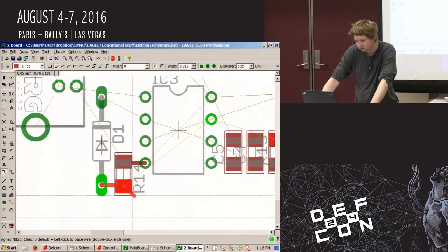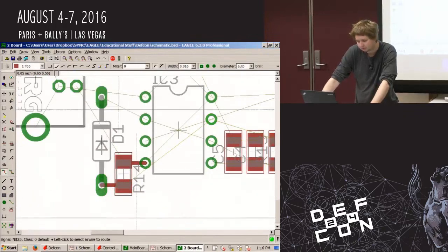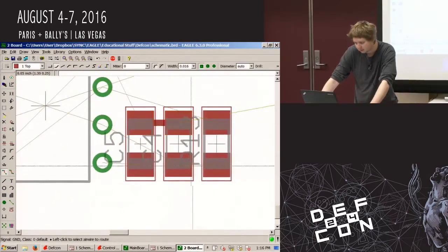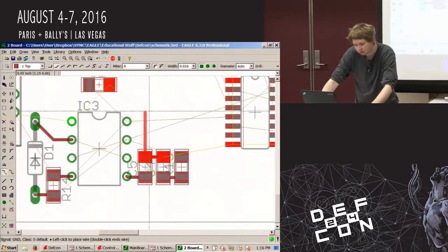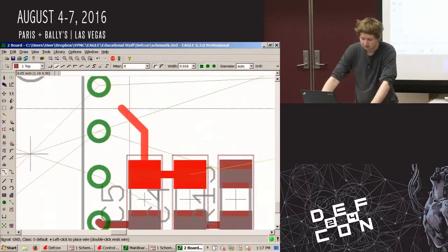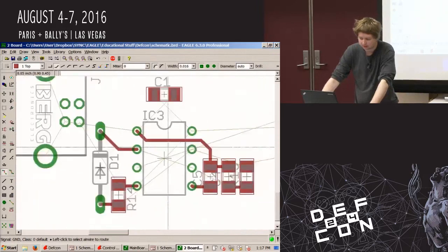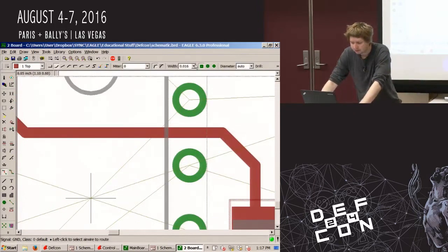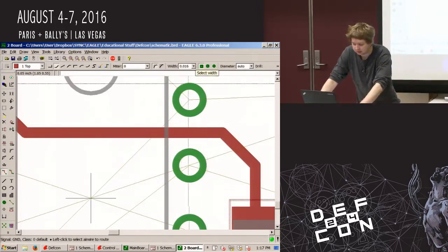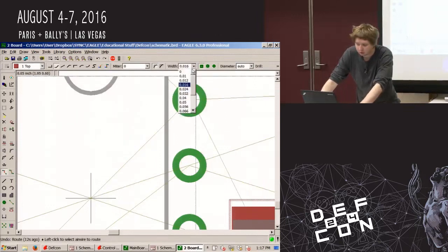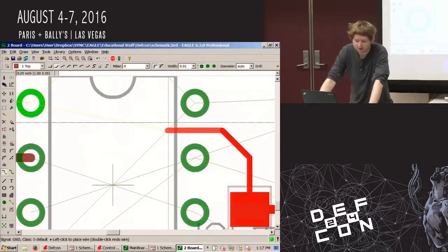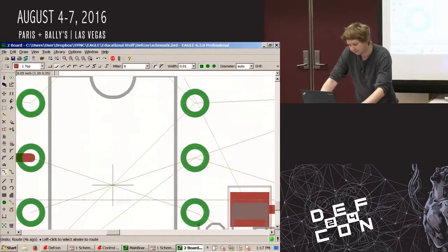So continuing on with routing, I have that diode again between resistors, so in this case I can go between traces right there. I need to be careful with how you actually do this. Sometimes if your pins are too close together, you just need to go through a smaller wire. Because this is all low current, I can use a 0.01 wire. That's typically as small as I go. But you can see I could probably fit 2 traces between there.